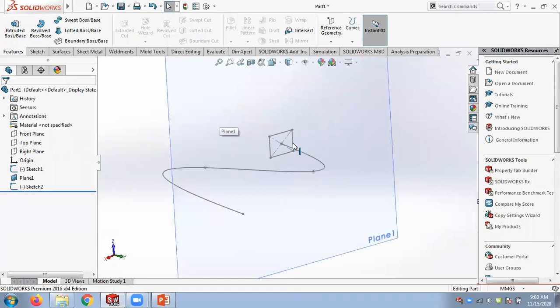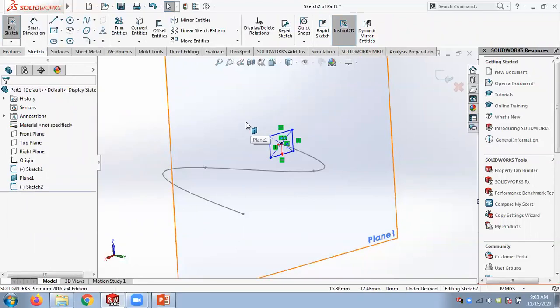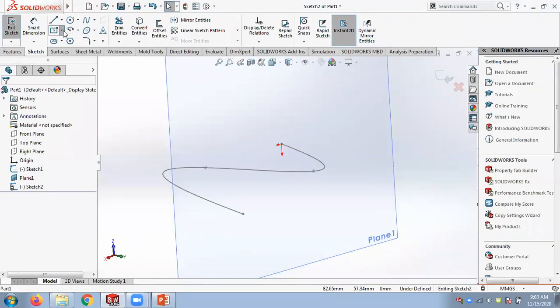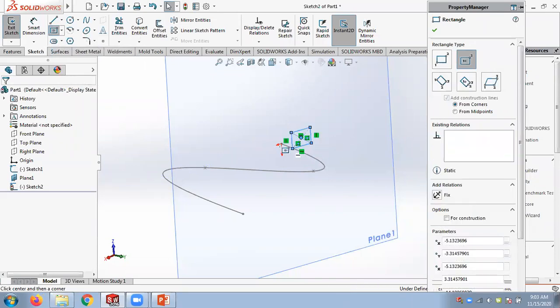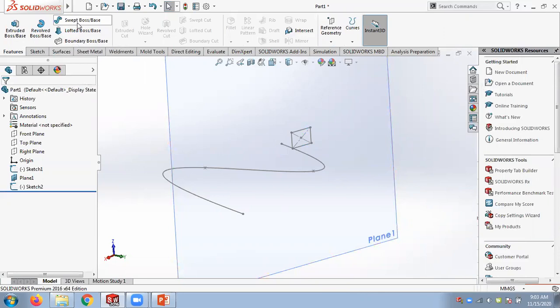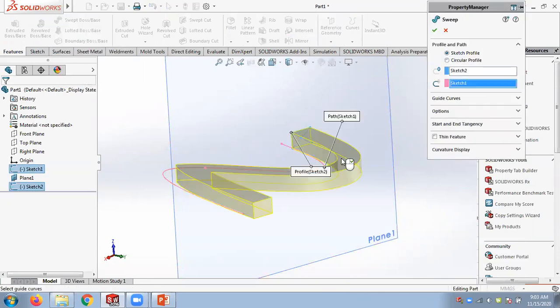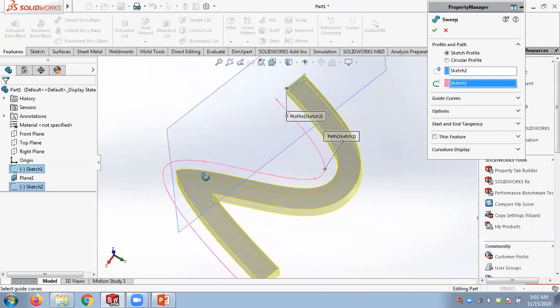Now I have drawn the profile exactly in the middle, so we will edit that. For the time being, I will delete this. So we can draw it somewhere offset to this. So you don't need to draw it exactly here. So I have drawn it off at an offset. Then we can run the sweep tool. Okay. So you can see the parallel profile has been created.